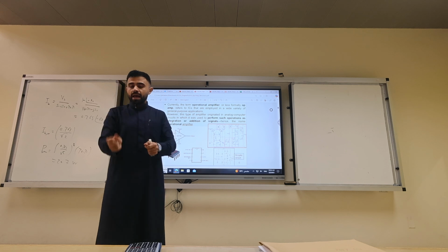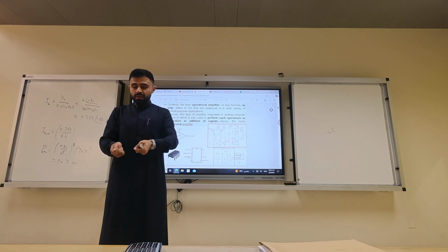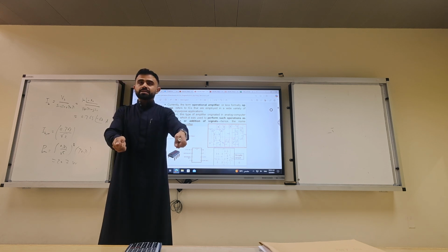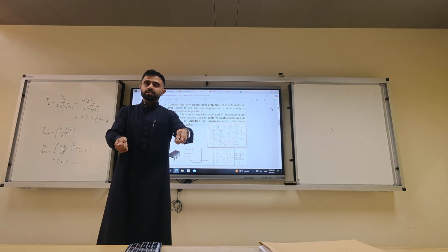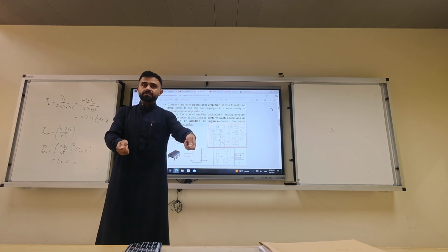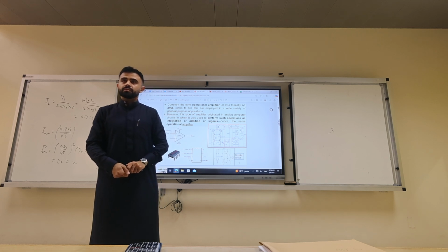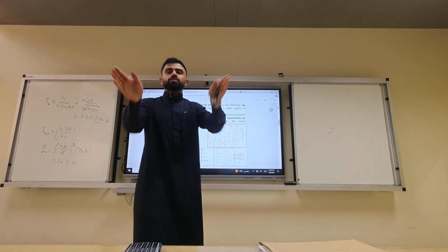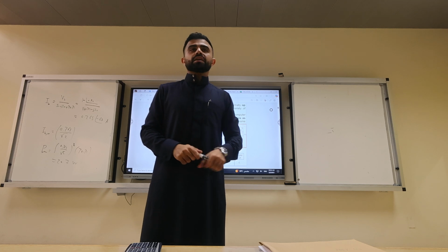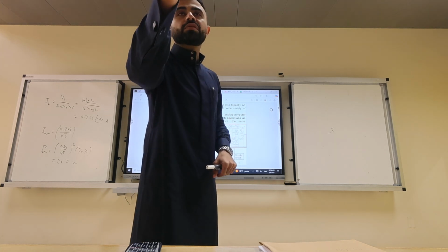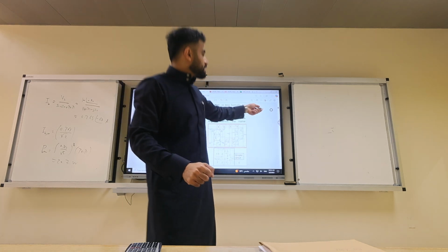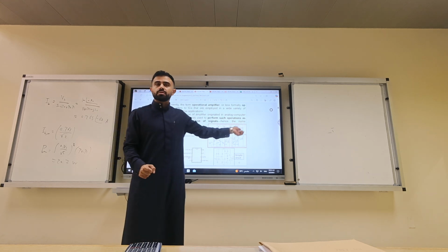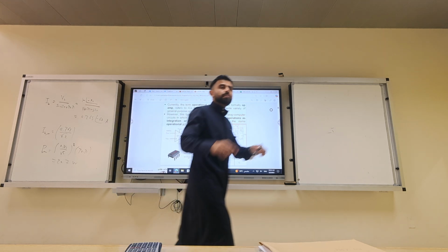Do you remember in the lab you have 5 volts, and if you connect it here, you'll get minus 10 volts or plus 10 volts, which is actually 5 minus minus 5. It's like you put two batteries opposite of each other. Get it? But this one is a single voltage source. This one, think of it as 2 voltage sources, two batteries opposite each other.